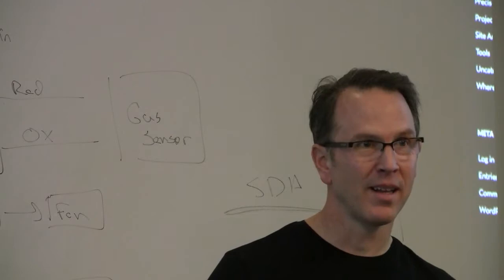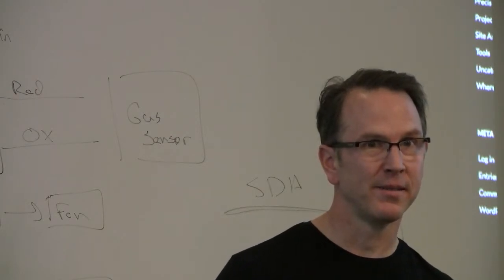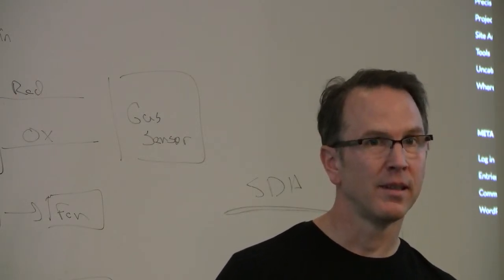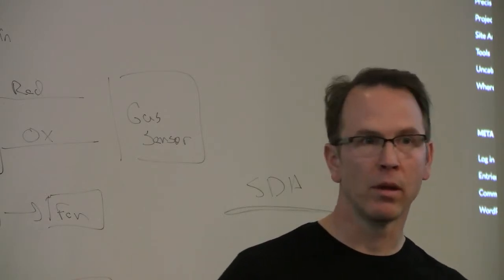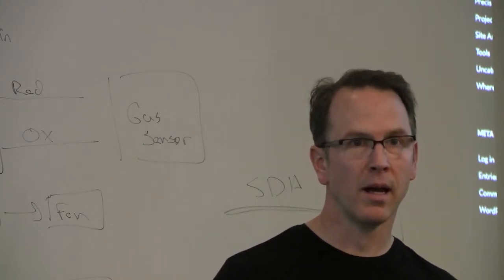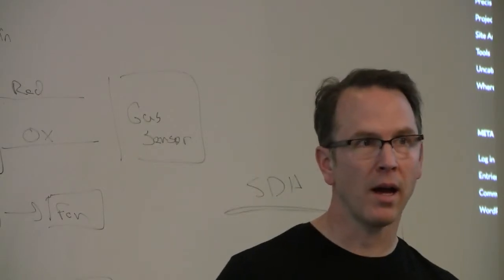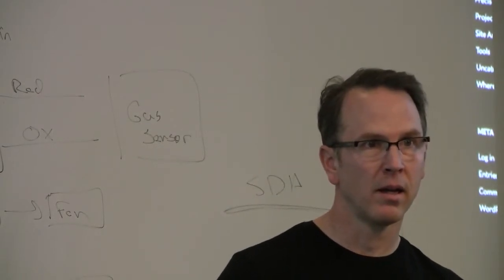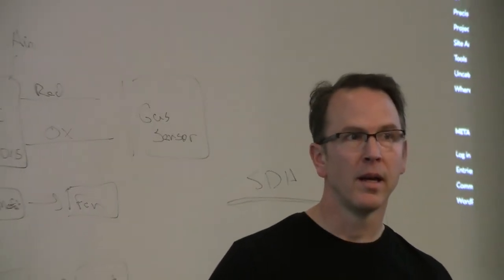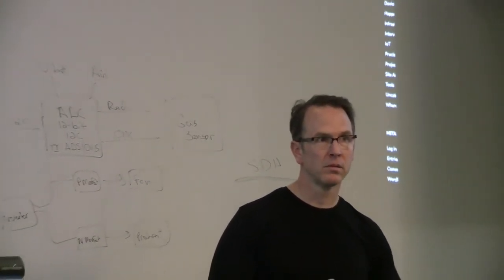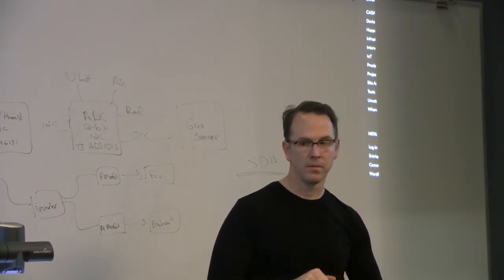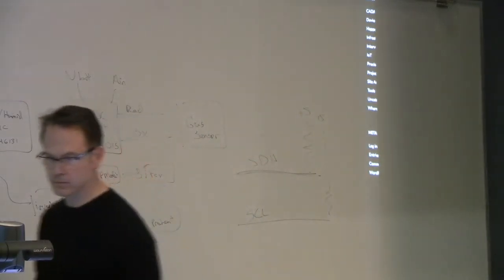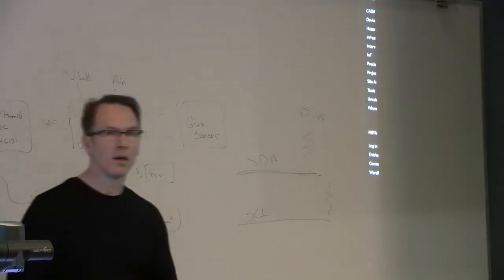Well, even though I'm not taking there's no signal other than those two going back to the Pi. But they always talk back and forth. But that's a big other than. Yeah, well, actually, they always, just because you think you're only sending something there, especially on I2C, it's going to be going both ways, regardless of what you're thinking. Because a lot of times it says, hey, I want address 68. Well, it's going to respond back and say, okay, I'm 68, I'm on the bus, send away. It's going both ways.